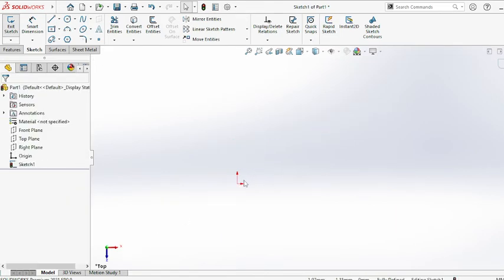What is black color, what is blue color, some yellow color is also there. Whenever you draw figures in SolidWorks, three colors are there: black, blue, and yellow. Blue color means the figure is underdefined. Underdefined means it is not fixed, so this figure needs some more dimensions. That figure will be in black color when it is fully defined, so all the dimensions have been applied.